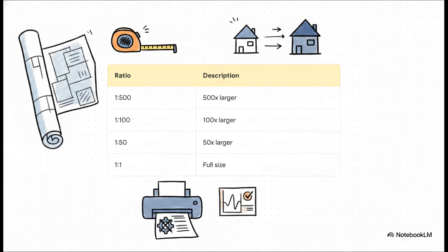But here is a massive pro tip for your career. When you print plans, you absolutely must make sure your printer's shrink or resize settings are totally turned off. If you don't, well, you ruin the original scale, and your measurements will be way off. And nobody wants to be the person who built a room too small for a bed.